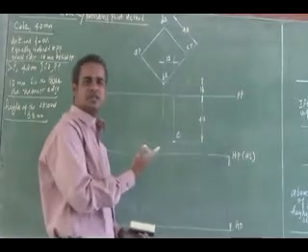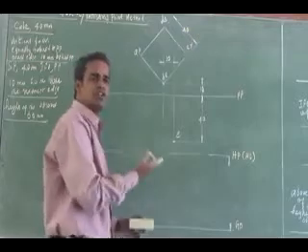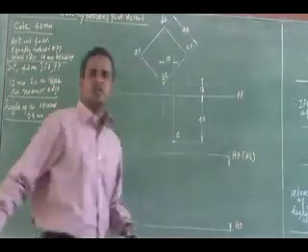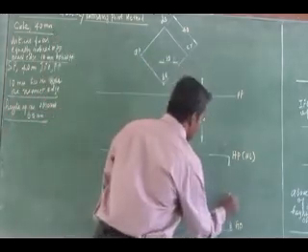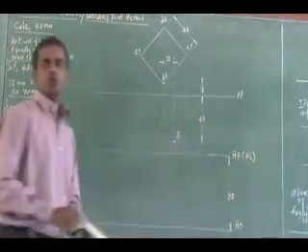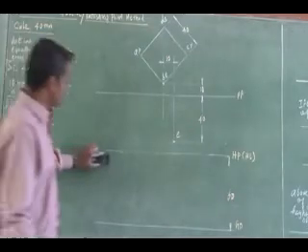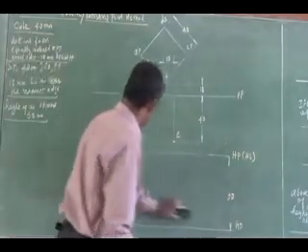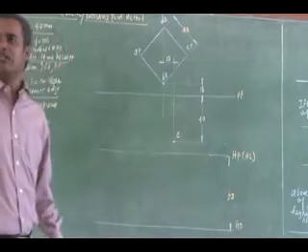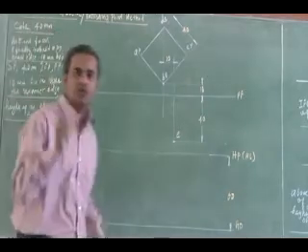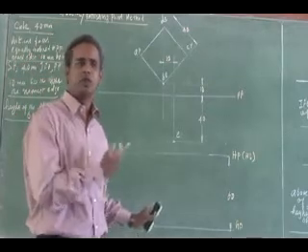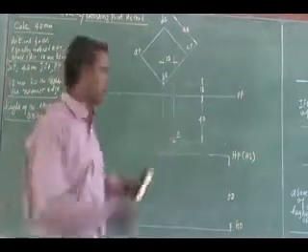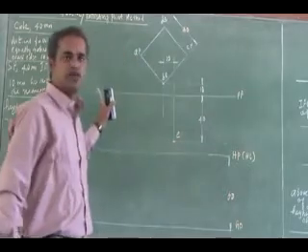That height of the observer, or the distance above the station point, is nothing but the horizon line I have to draw. So that is 60 mm. Right, so we have to do this. Once this is over, listen all of you, not like the previous one, I have to try to get vanishing points. This is 2-point perspective, so I have to get two vanishing points, a right side vanishing point and a left side vanishing point.